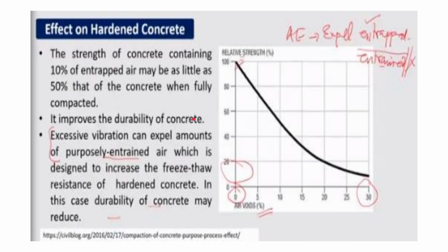So why is compaction important? Because as you can see in this picture, even if there is about 10% of entrapped air, the compressive strength falls by 15%. So that's why entrapped air is a real nuisance. It is not good for concrete.